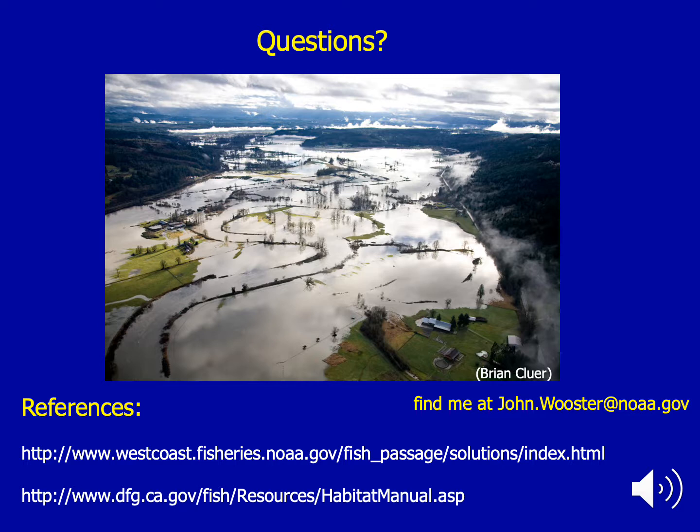design. So what are we doing in the field? We're looking for multiple active channel and bankfull channel measurements. You're looking for your valley width. You're identifying floodplain versus terrace. We're looking for bank erosion, and if you have bank erosion, why? What's the cause of that? Generally looking for bank erosion on both sides. Do we have evidence of overtopping the bankfull channel? Is there floodplain connection?